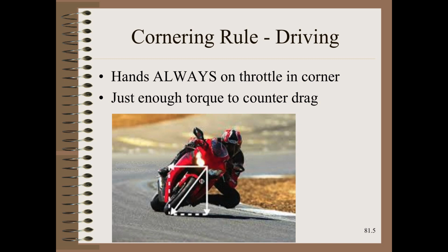So now let's put this learning to practical, everyday use. When in a corner, we do not want to put our foot on the brake. It is a deadly habit, whether on a motorcycle, in a race car, or even in your family car. The hand is safe only when it is on the throttle. However, zero throttle is not what we want. What we want is just enough throttle to tend to neither speed up nor slow down. In other words, just enough to counter drag.